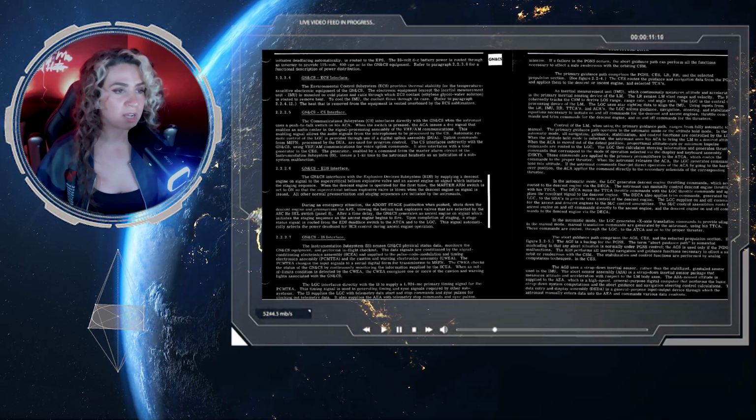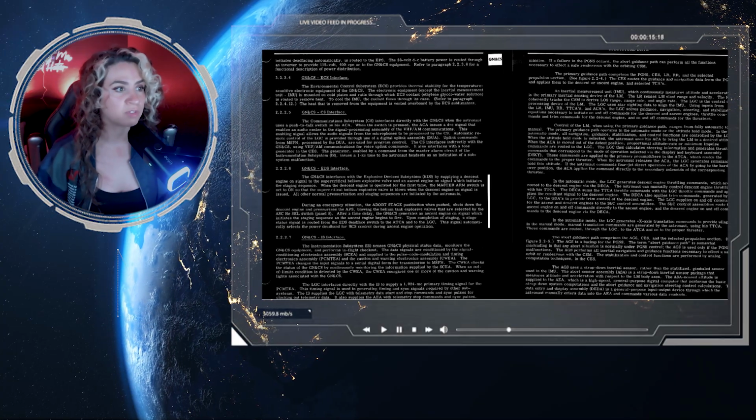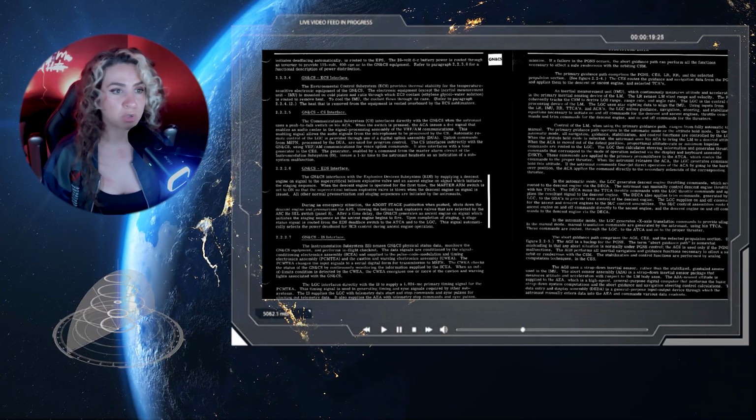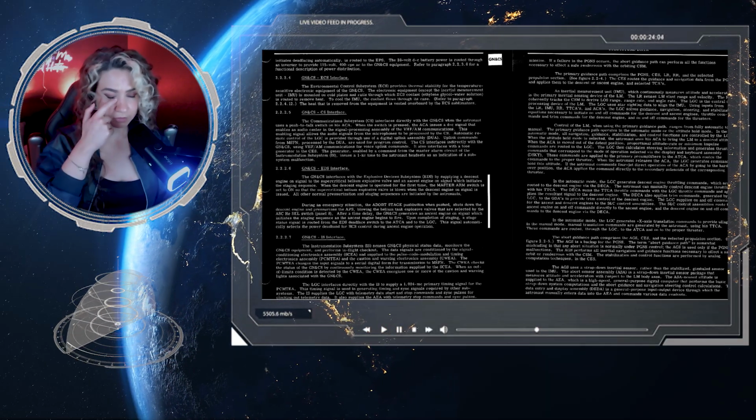If the astronaut commands jet direct operation of the ACA by going to the hard over position, the ACA applies the command directly to the secondary solenoids of the corresponding thrusters.